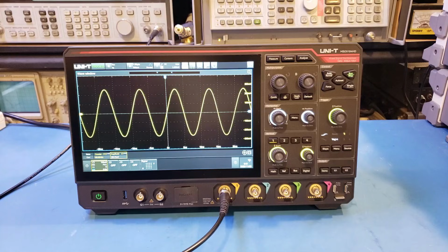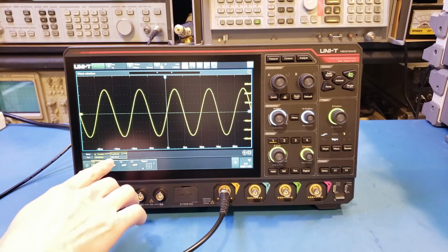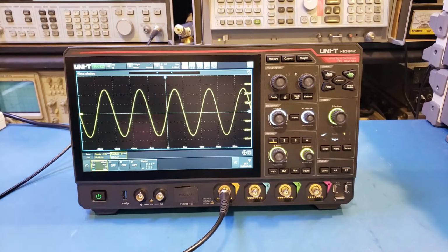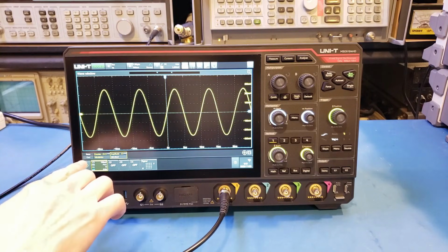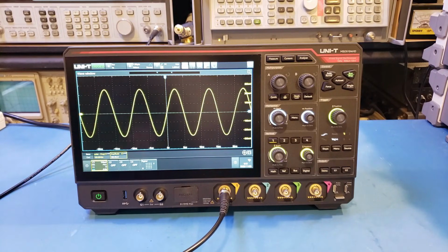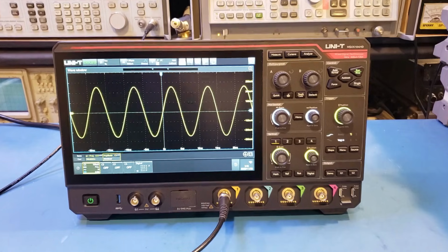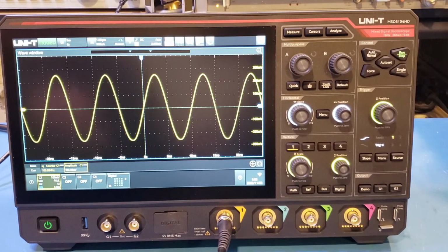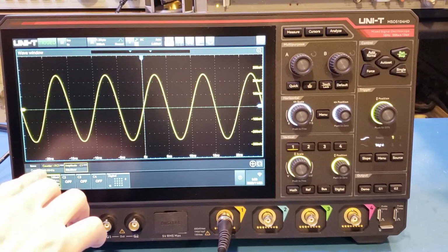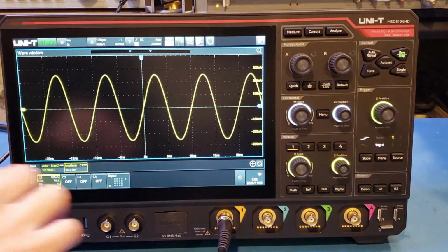Alright, right now you can hear the 8642B humming in the background, and currently it's outputting a 100 MHz signal. I adjusted the output amplitude so that it is roughly at 500 millivolts, so that later on when we test the bandwidth, we can easily figure out the bandwidth limit at roughly 350 millivolts. Anyway, I've also turned on the hardware counter. You can see here, it is currently at 100 MHz. Let me just zoom in quickly for you. And you can see in this close-up, we have the measured frequency and also the amplitude right at the bottom.